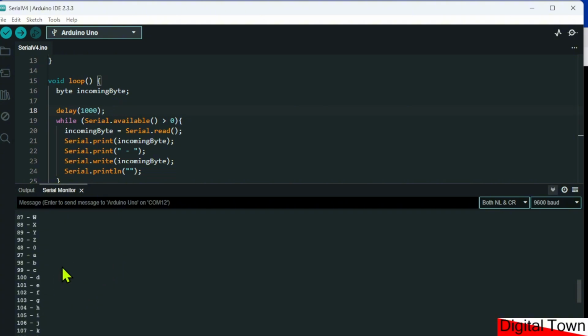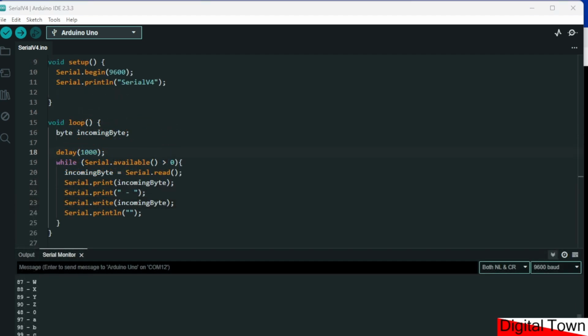It means that when you are receiving data, you need to make sure that you are clearing the buffer as quickly as possible, even if you then have to put it in your own buffer. So I'm going to end this lesson here just to prevent it from becoming too long.